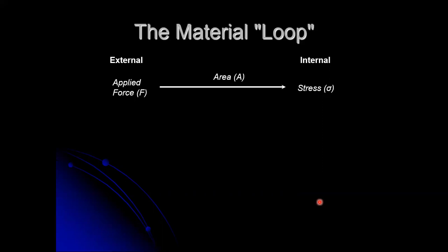Well, once we know the stress, we know a lot about what's going on. We can go to a table and say, well, I want to try and put 20 kips on this member. It's got a 10 square inch area, so 2 kips per square inch. And I want to make it out of 2024 T6. So I go to my table and I find out, well, what's the maximum amount of stress that 2024 T6 can handle? And if 2 kips per square inch, 2 KSI, is below that, I'm good. That's always a very important check to make.